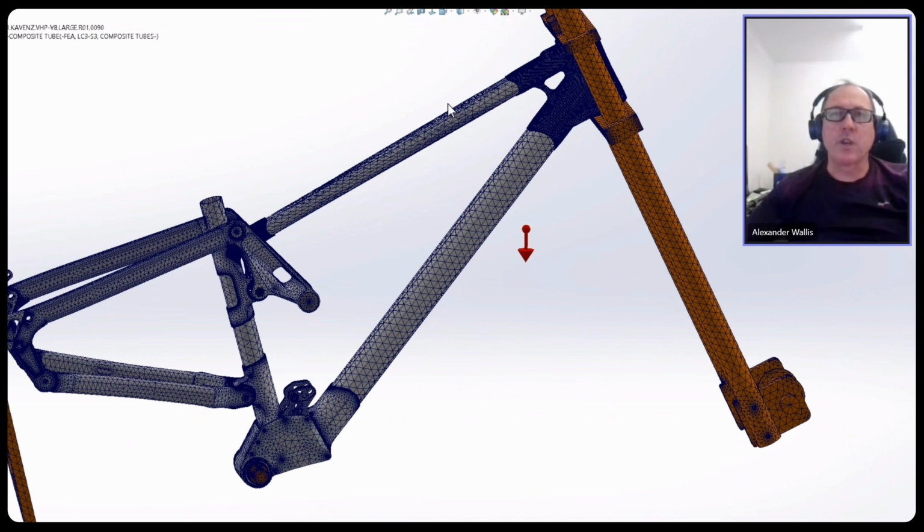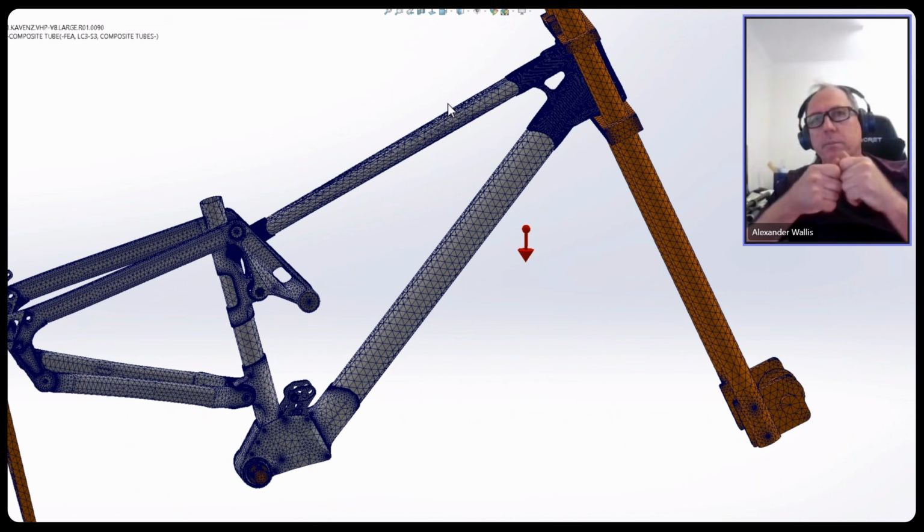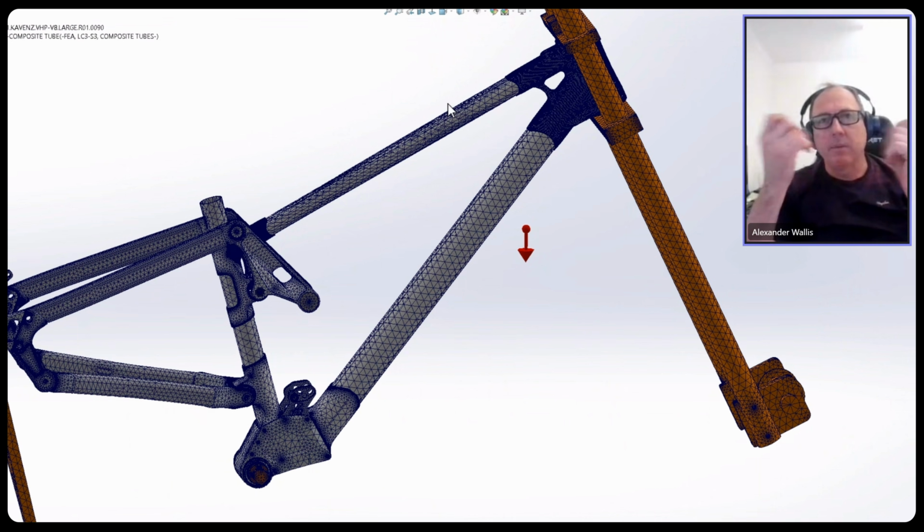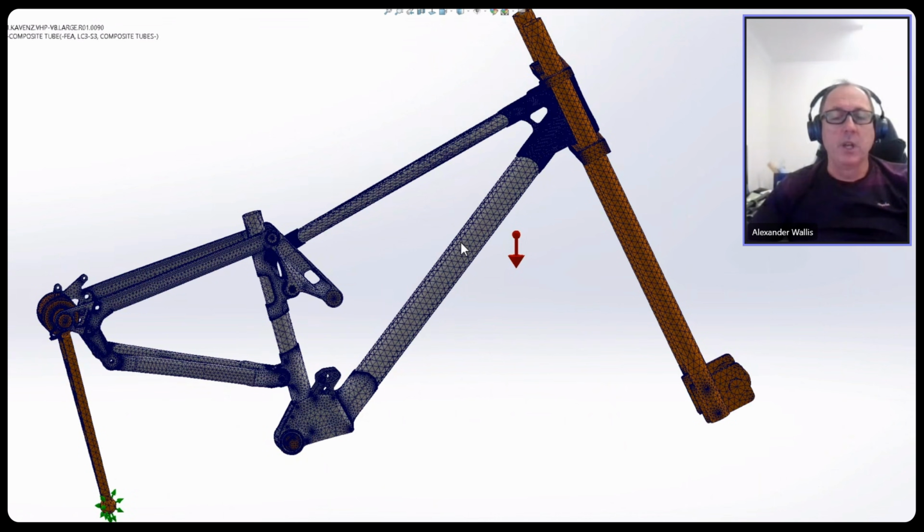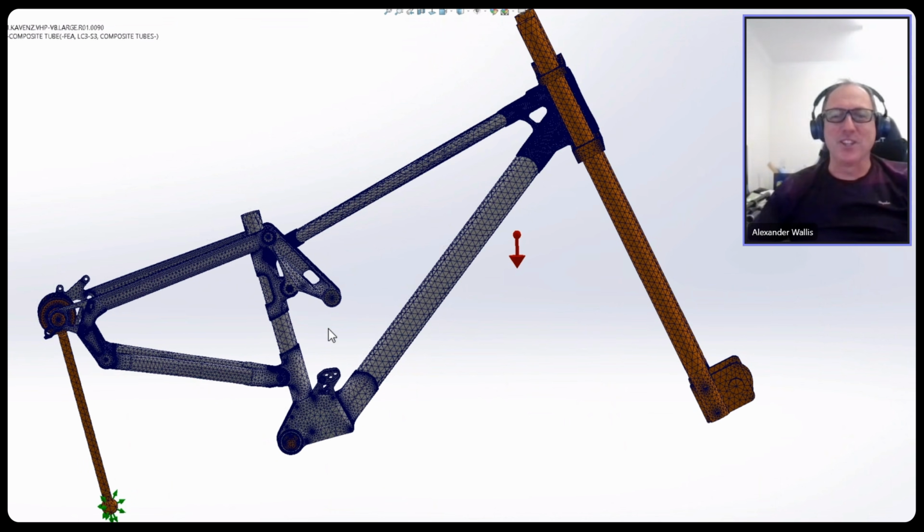We call that strain, and strain becomes known as stress, which is the pressure in the material. That tells you how hard the structure is working, and all materials have a limit, a point where they will no longer take any more load and no longer behave like a spring. They start plastically deforming, and hence they get to a point where they deform and break. This is what these finite element calculations are all about. They allow us to do very complex calculations in a matter of hours, which would have taken us a matter of years. 30 years ago, this would have been a fairly long calculation.